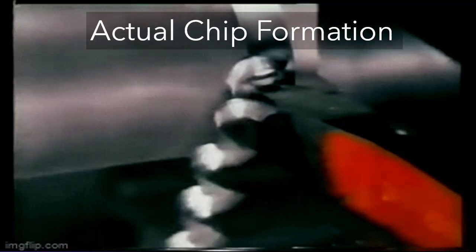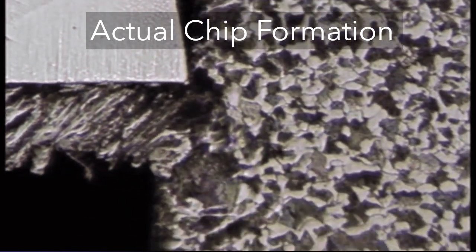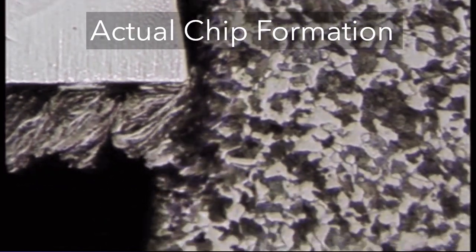There are differences between the orthogonal model and actual machining processes. First, the shear deformation process does not occur along a plane, but within a zone. If the shearing were to take place across a plane of zero thickness, it would imply that the shearing action must occur instantaneously as it passes through the plane, rather than over some finite time period. For the material to behave in a realistic way, the shear deformation must occur within a thin shear zone.